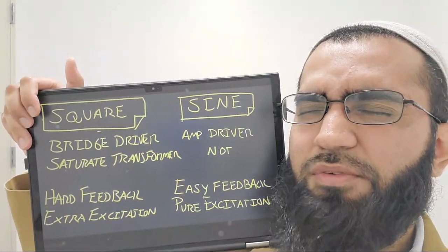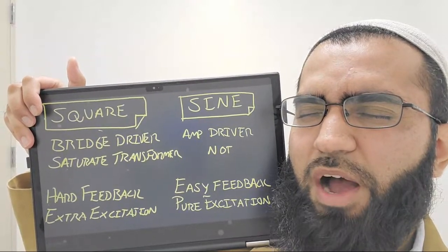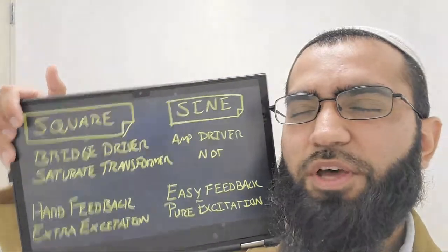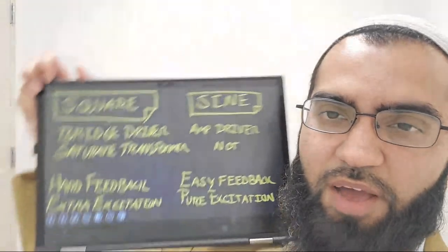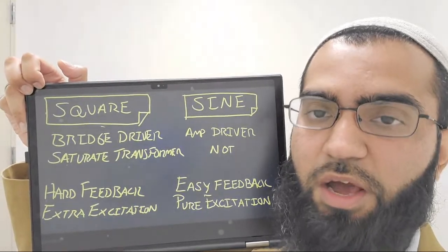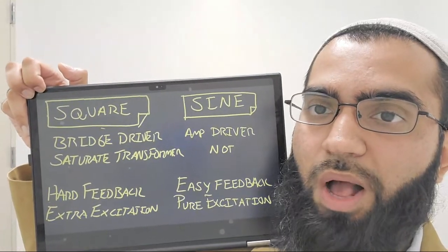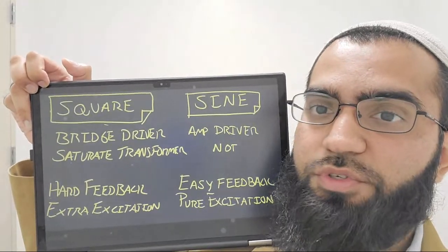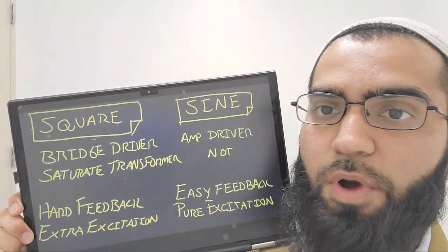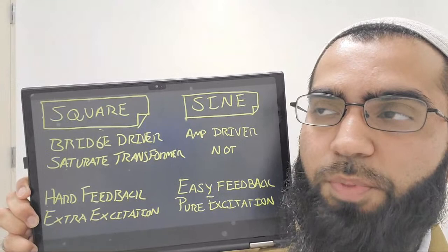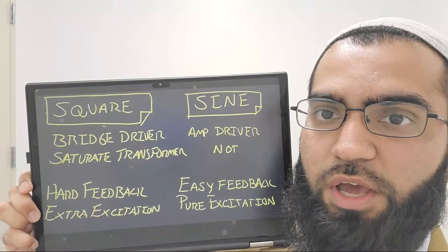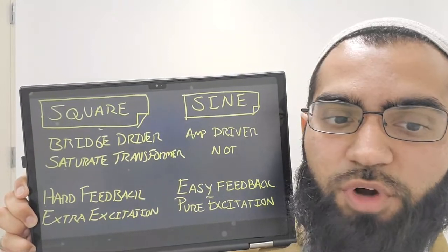I'm not sure, but I believe ultrasonic, like high frequency drivers, for ultrasound diagnostic applications, I believe they use square waves. I haven't worked on those specifically, so I can't speak perfectly, but I think they always use square waves, and a good reason for that would be, well, you can hit high frequencies, and you can have a simple enough drive topology to drive multiple channels with ease. But for power ultrasonics, sub 1 kilohertz, 100 kilohertz, yeah, you're gonna benefit a lot from using a sine wave style driver if you can.